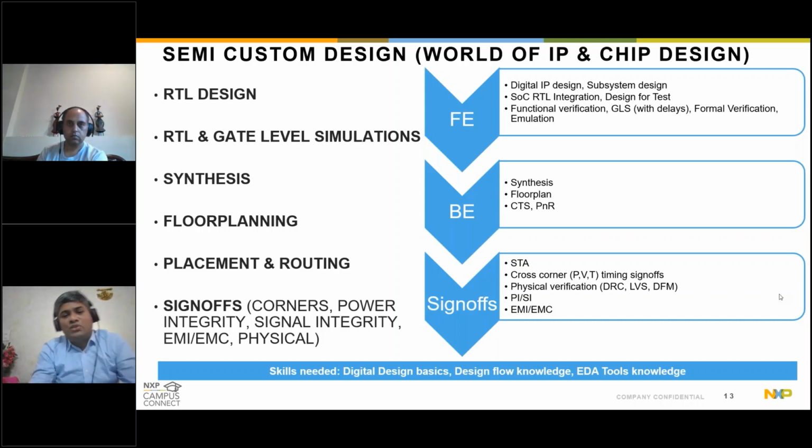So this printability on the wafer is done by the back-end cycle, where the RTL netlist is synthesized into gate-level netlists, where the real gates, right? What we talked about in the full custom design, the ANDs and inverters and buffers and NORs and flip-flops, everything starts to take their physical shape, right? We are now going one level of abstraction below.